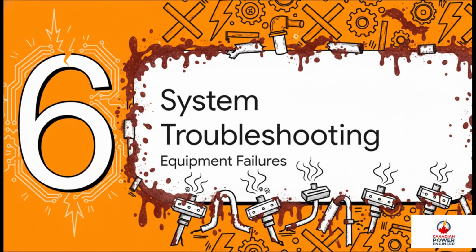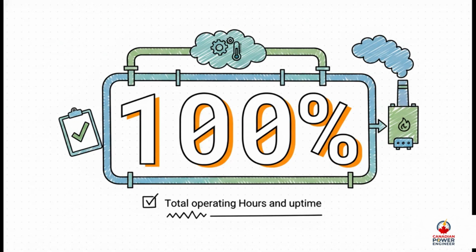Wrapping things up with Section 6, System Failure Troubleshooting. Now, what's really interesting about this is that perfectly balanced 100. It represents perfect system availability. The SEAMS equipment is incredibly tough, sure, but it's operating in a harsh, corrosive environment. When the monitoring equipment breaks down, you need to know that environmental monitoring has a strictly defined legal minimum availability. The formula is the total operating hours where the system provided quality-assured data, divided by the total plant operating hours, multiplied by 100 to get a percentage. Simply put, if your boiler is running, your SEAMS better be running and providing verified data. If it's not, from a strict regulatory standpoint, you essentially have zero environmental monitoring.